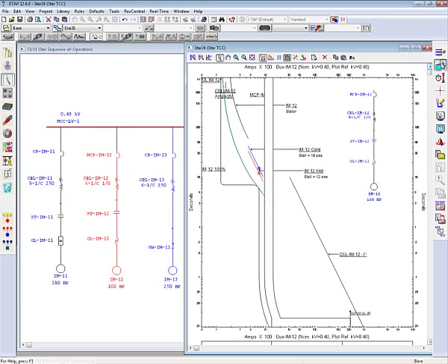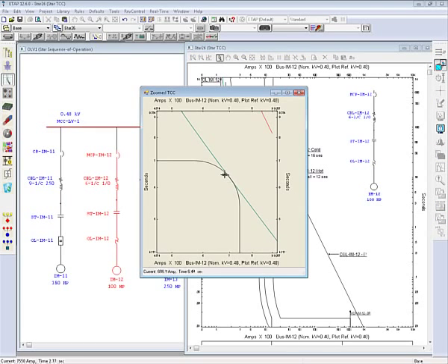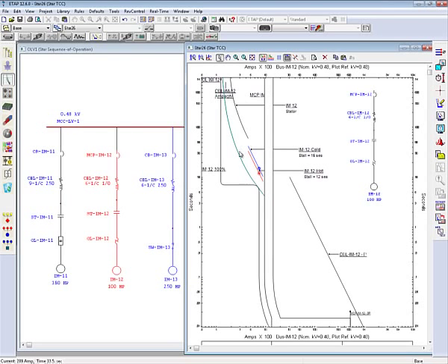So if I take a zoom window and look at this overload heater intersection, I can see these two curves are intersecting, and probably the overload heater curve will not allow the motor to accelerate to reach the full load capacity of the motor. Again, I need to play with the setting of this overload heater in such a way that it clears off the starting curve.